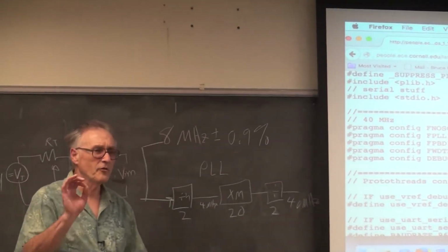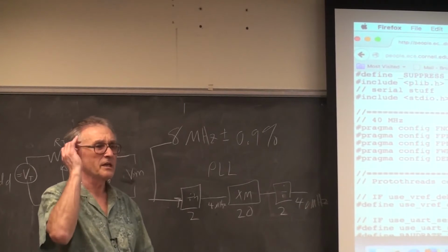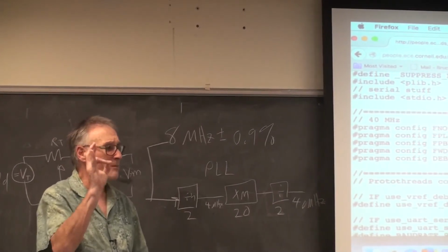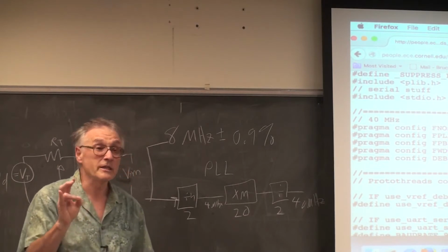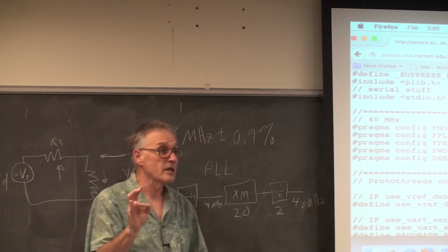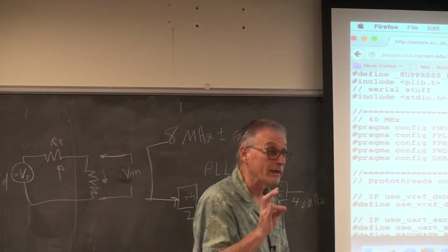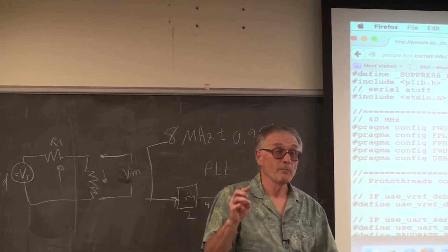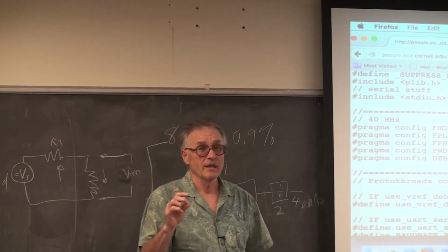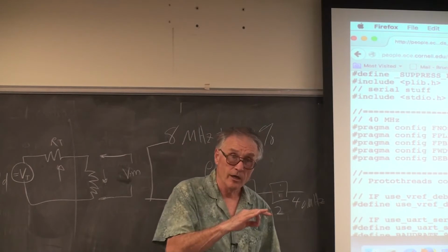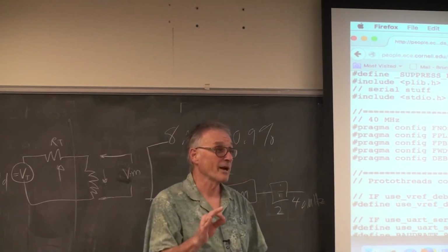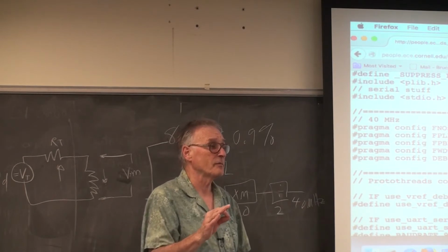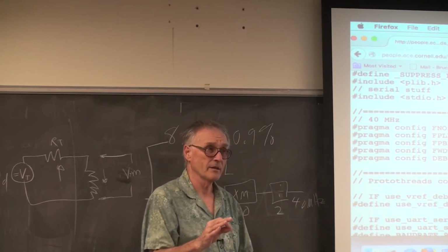So the CPU frequency of this config file is 40 megahertz. You could change that. You can change it to anything you want up to 80 megahertz, except the CPU won't run at 80 megahertz. It may well run at 60 or even 64. It probably will not run at 70. It's rated at 50. The closest you can get with the PLL is 48.